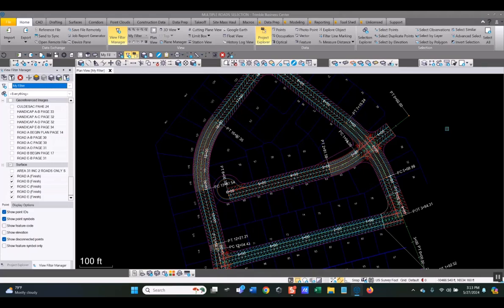But in using the control key, you have to pick one entity first. Okay, I got one. Then you press and hold control, and now you can pick the onesie twosies entity. You can also, if you inadvertently, oh, I didn't want these two out here. As long as you press and hold control, you can pick a highlighted entity to unselect it or unhighlight it. All right?